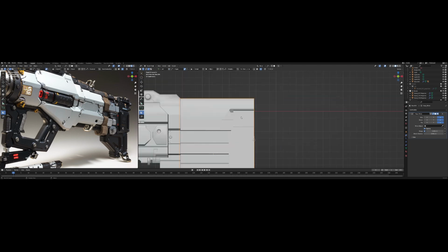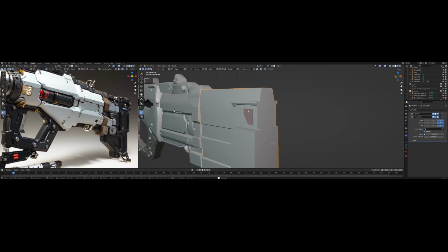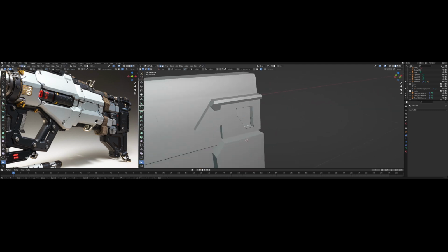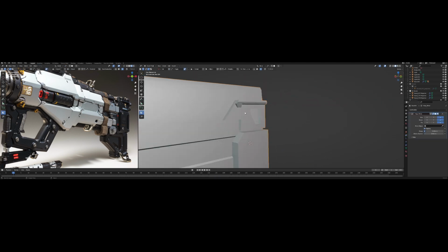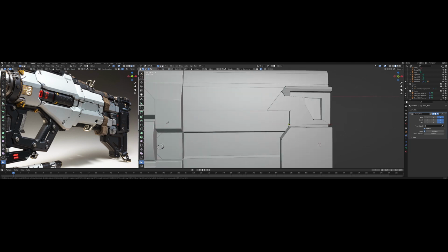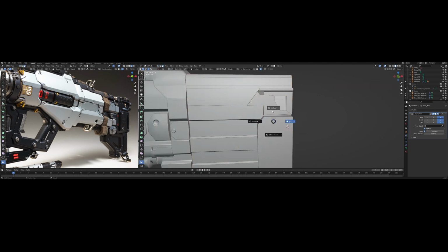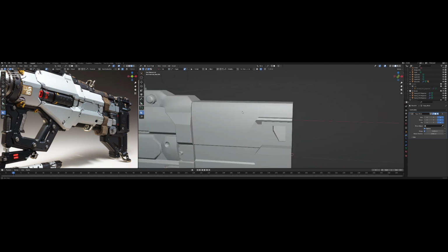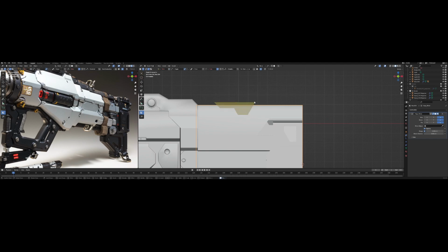And if you want to flatten those shapes, we can just press W and then select flatten. Before this function is activated, we need to make sure that the LoopTools add-on has already been activated in our add-on files. So now let's take a look at the general part of it, to see if it really fits the picture.